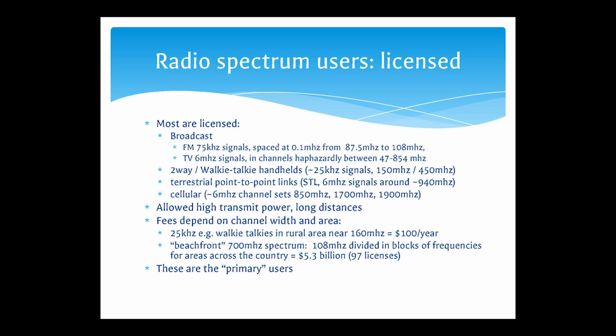Two-ways or walkie-talkies are another popular use. Those use very little bandwidth, say 25 kilohertz wide. And often those are licensed around frequencies of 150 to 450 megahertz. They tend to fall into those ranges for a few reasons, usually the ease of manufacturing hardware.